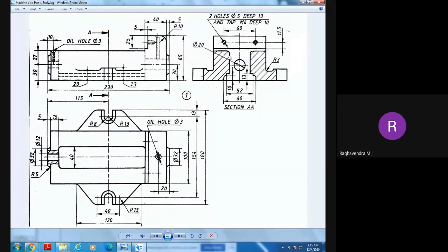So before going to that, let me construct the profile in the side view like this. We need to cut the part throughout this length here. Are you able to see this here? This is a cutout which is made looking from the top. But in the side view, looking from here, this is a view which we are going to get here. Okay. So this cutout width is 60, and here from here to here it is 52. Okay. And once again, this height is 10, and this side is 13. Okay. And up to here means up to 30 plus 27, up to 57, that is up to this side. We need to cut this shape.